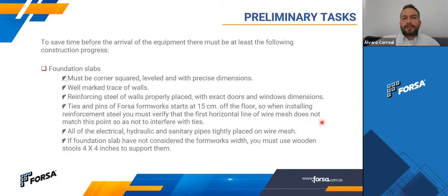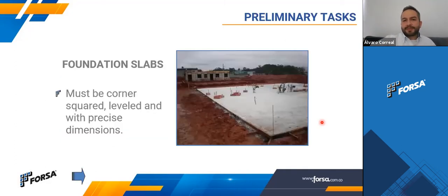Okay, so before the arrival or before you start working with the set, you need to check and to do some activities on the foundation slabs. This is a perfect example. They must be cornered, they must be squared, leveled. This is very important, and I'm going to be very repetitive with that, and to have precise dimensions.